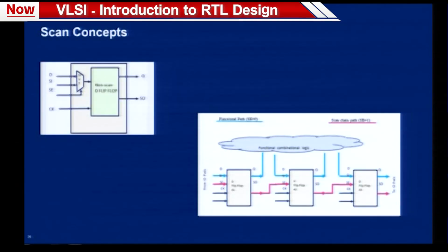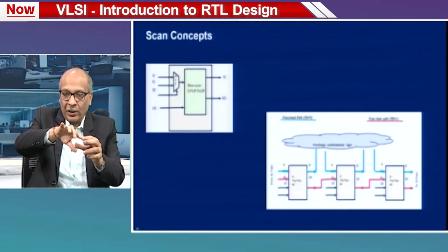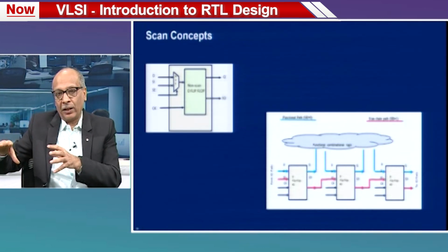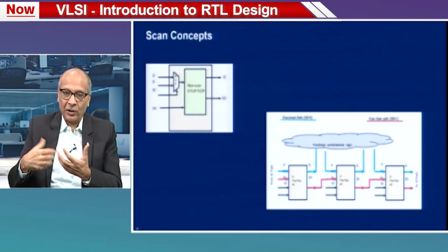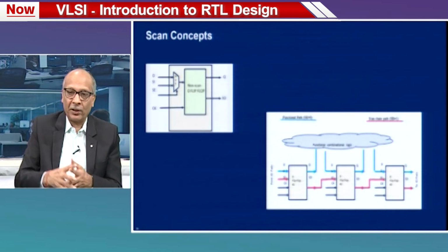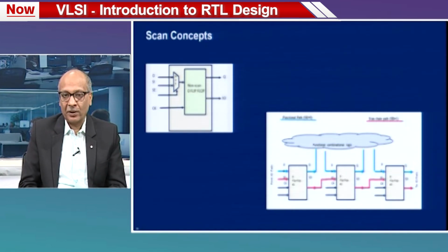When we started our presentation, the first slide was: you get each die and test it. Okay. Test it how? Using these methods. You put it into the tester, apply the vectors, and those vectors will exercise all the paths that are of interest. You read back the value. If the value is what you wanted, then you know that your device is working correctly, else discard it.